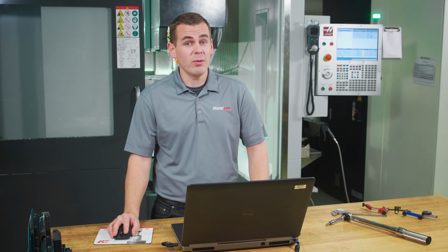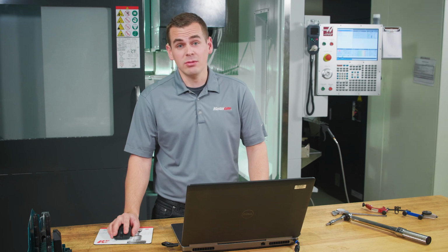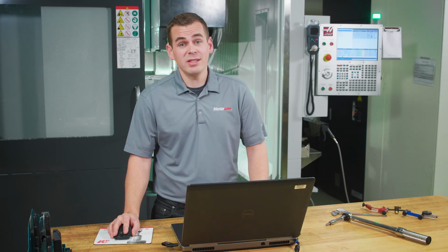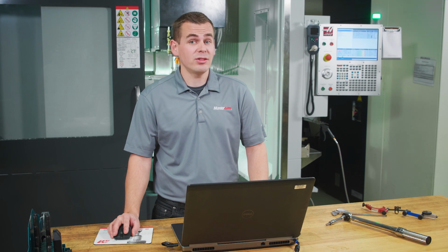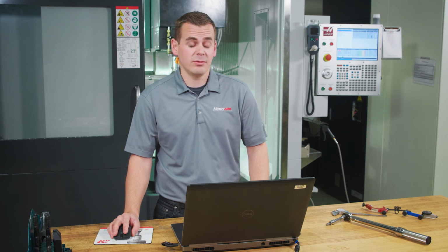However, with most modern machine tools with high-speed machining algorithms, this is only half the story. It's imperative that we also communicate to the control how accurate we want these parts, and to cut them as quickly as possible. To do this on the Haas, we're using G187. This can be controlled via miscellaneous values in Mastercam when using any of the default Mastercam Haas post-processors.